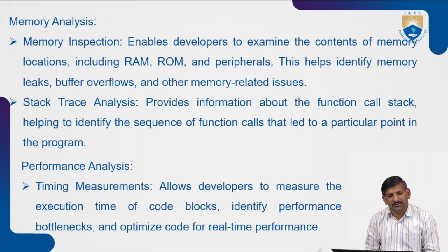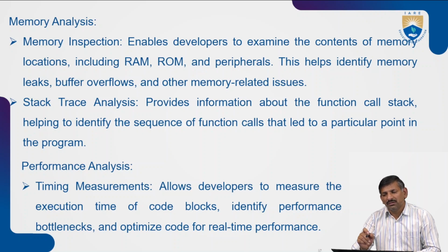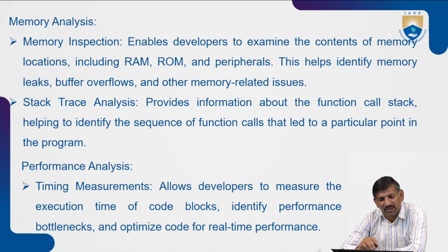Next, memory inspection, memory analysis. It enables the developer to examine the contents of memory locations, including RAM, ROM, and peripherals. This helps identify memory leaks, buffer overflows, and other memory related issues. So here time is important. If the buffer is full and the data is not received at the destination properly within the time, what happens? We may lose life and property.